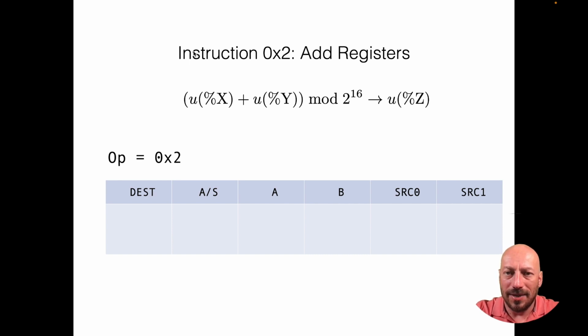Here we again have this bit pattern set, identifying the destination register. So I already kind of smell an opportunity to optimize away one of these multiplexers. We again use an addition, and the bit pattern of A, for example, should be the bit pattern of the register with ID X, and that means the register bank should select this register, and the bit pattern for the other operand would be the bit pattern of the register with ID Y. So we also select this.